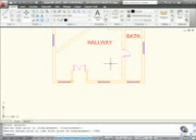So as you can see there, your stretch command is very useful. Use a crossing selection, so at the select objects prompt type C and enter, or use a crossing polygon selection by typing CP and then enter at the select objects prompt.